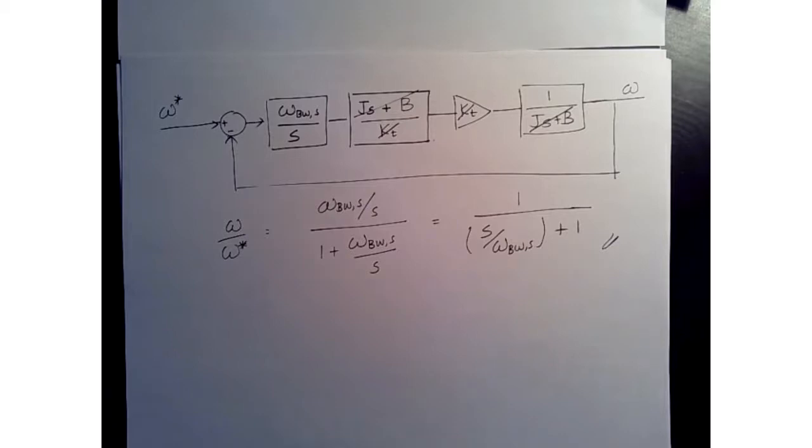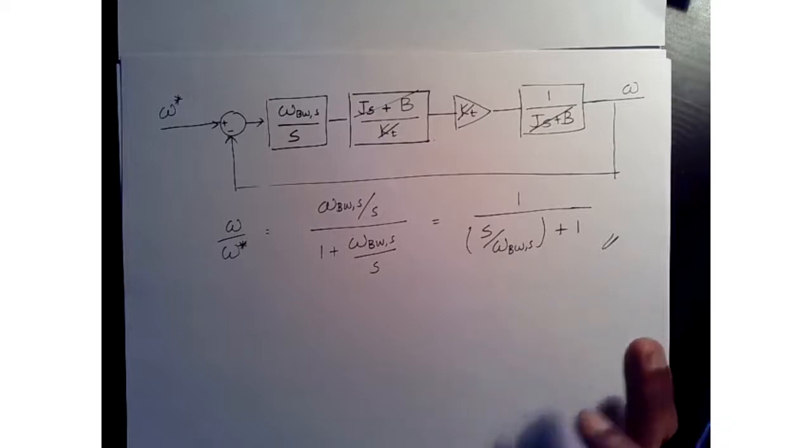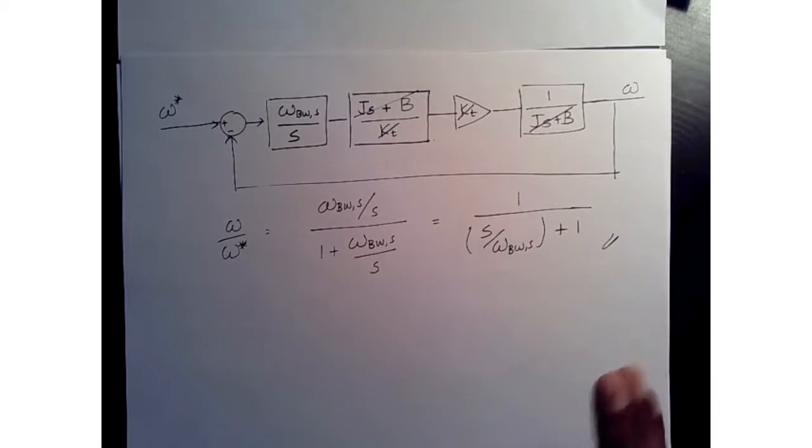Okay, same goes for here. If you change your inertia, if you change your damping ratio, let's say you change your fan design for a speed controller, now your controller is not going to operate as you expected. It'll have a second order response, and the behavior might be different from what it used to be. So you have to recharacterize if you change those physical or underlying system characteristics.